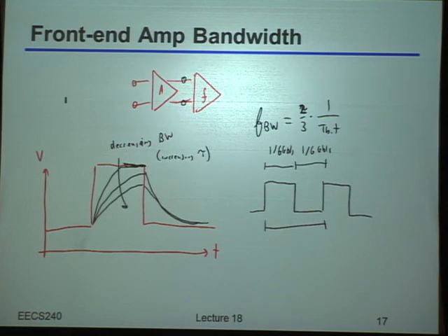If you then do a more detailed optimization, you'll find that this 2/3 number is basically about right. And that's for the overall bandwidth. That's really balancing out not just the settling error, but even the residual intersymbol interference, so the residual time spread we were talking about a second ago. Yes?